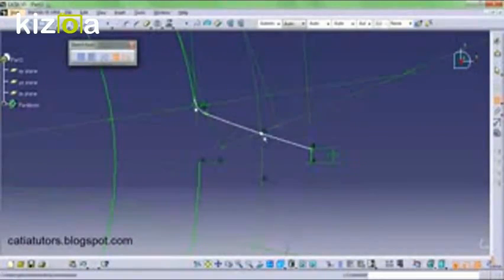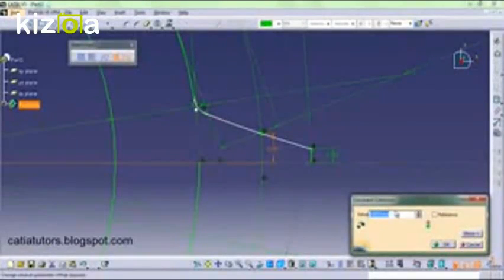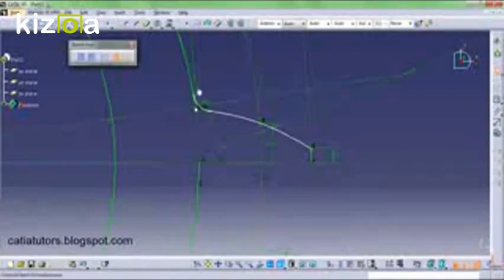So go to this, click on this point and click on this line, and again we need to change the distance. So double click on this, and this time we need to change this distance to 0.2618 divided by 2 and click OK. Okay, so here we have the changed dimensions, and there is one more detail that we need to add. We need to make a mirror of the geometry which we have made here.